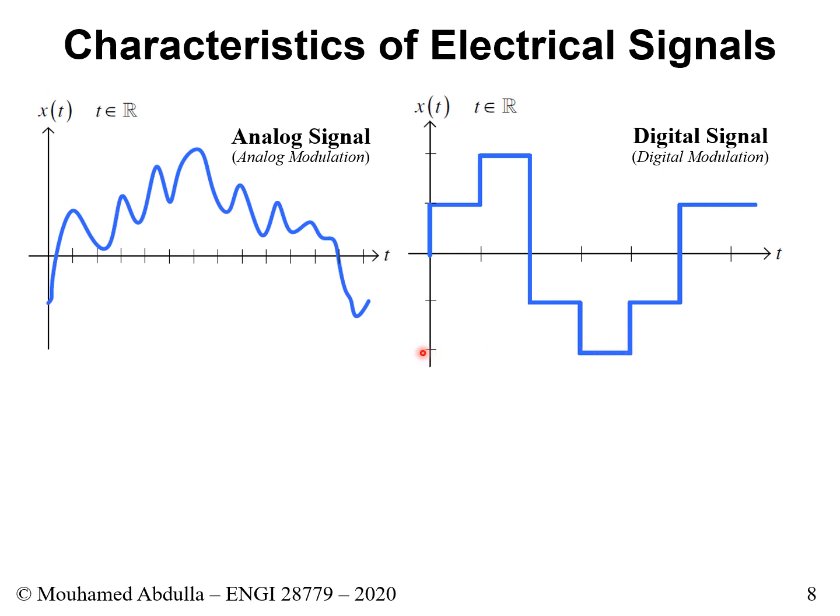So anytime you have a voltage that represents this, what enters a digital modulator is basically 0, 0. This level, you could enter in the digital modulator as 0, 1. This level as 1, 0. This level as 1, 1. Okay, so that kind of gives you a sense of that.